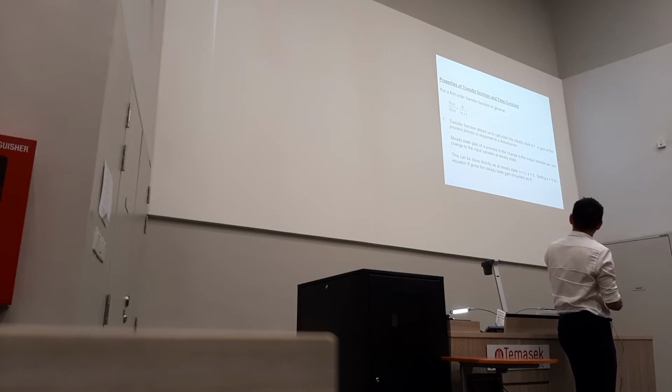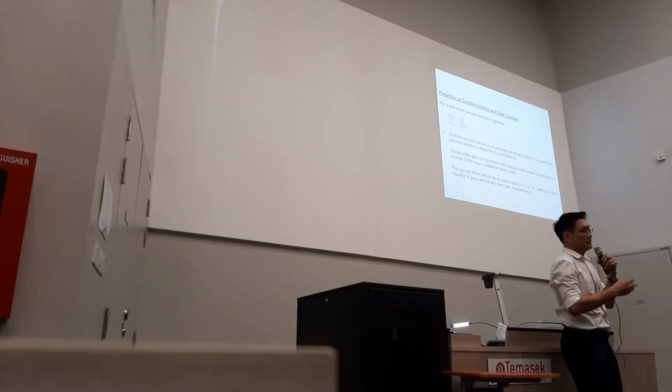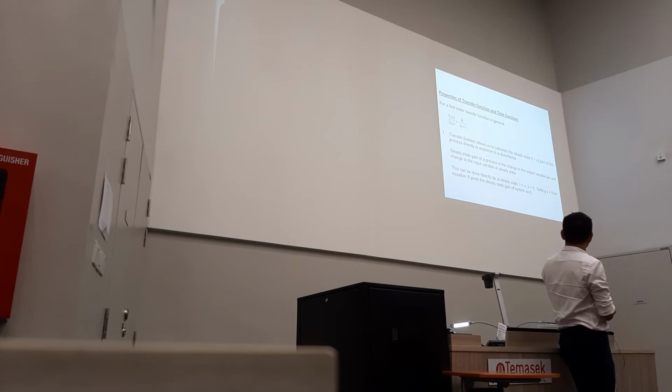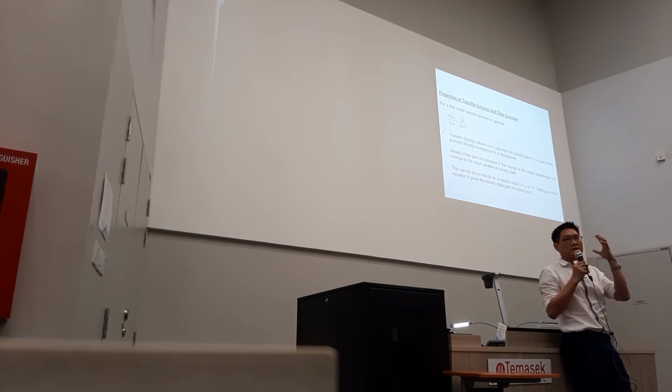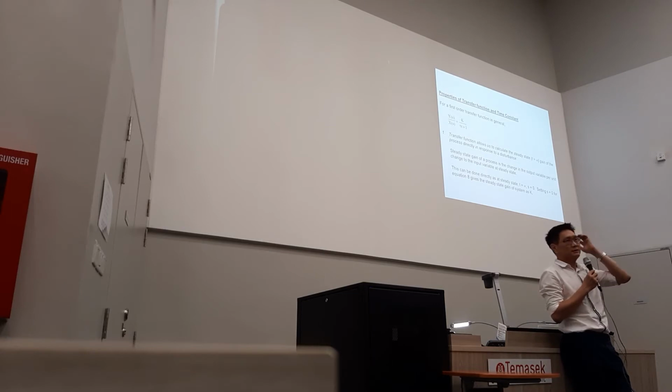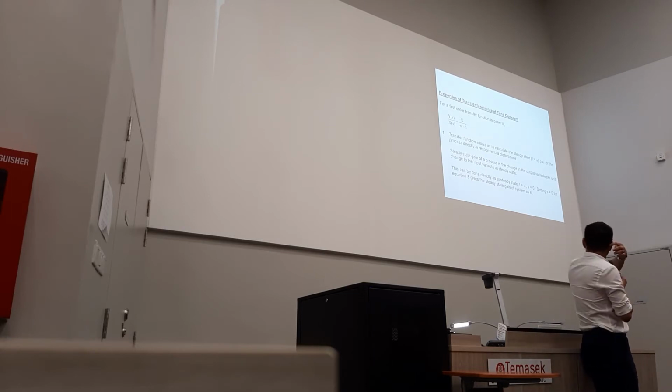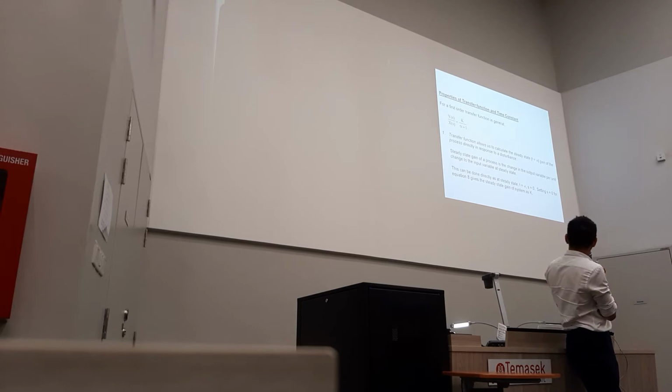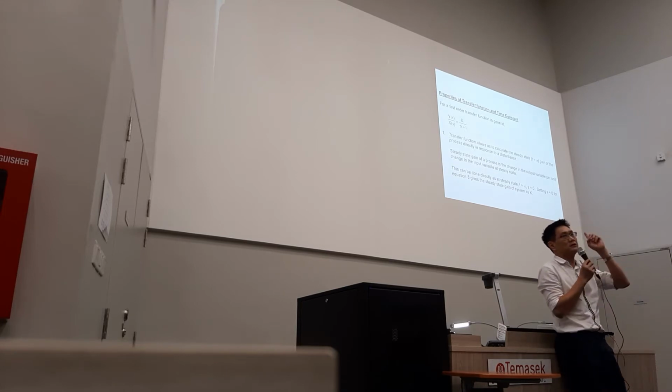Actually, the gain is more important. The steady state is just a reference, but K actually refers to the gain. Tau is the time constant, and s is the variable in the Laplace form, plus 1. Okay, this is our first order transfer function.